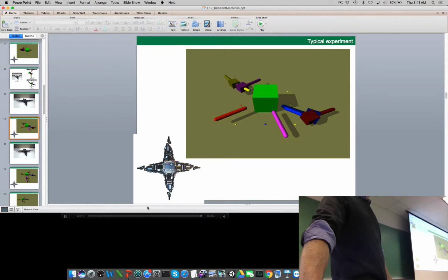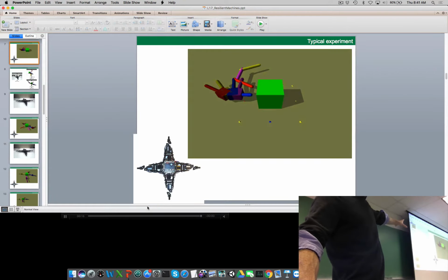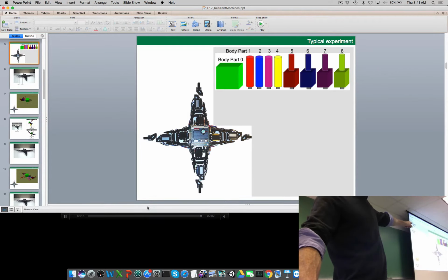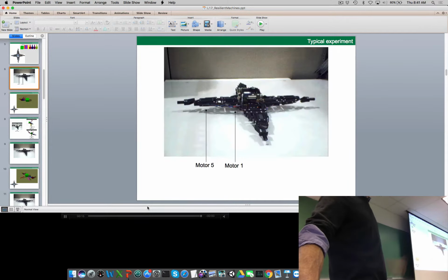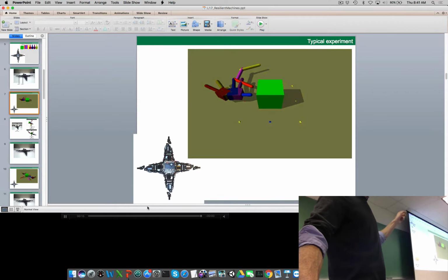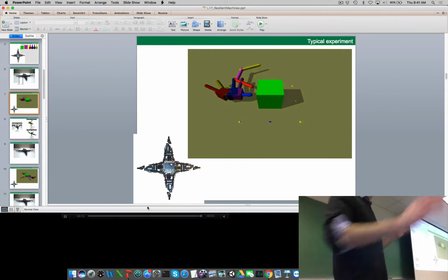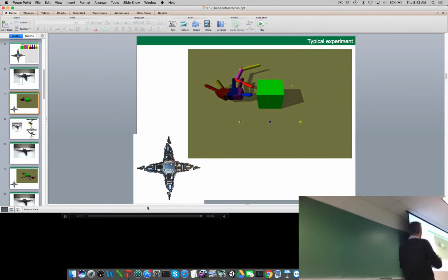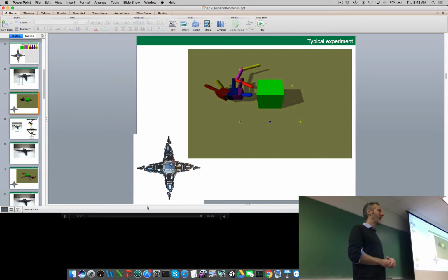Something's changed. Not yet. We're still dealing with the intact robot, right? We're assuming the intact robot, all it knows about itself is this. It doesn't even have a simulation of self yet. It performs one random action. Oh, it's trying to collect data. So it's going back and forth, the physical robot, the virtual robot. It's performed one action. It's evolved a population of these things that are all different, and they all match the single piece of sensor data that's come back from the physical robot. So it needs more information.